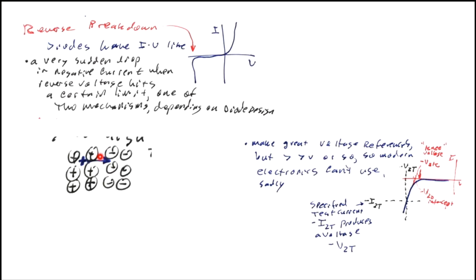And as that hole is accelerated across, it can get a lot of energy. Acceleration: the longer you keep accelerating it, the higher its energy becomes, right? It'll go faster and faster, and it'll get more and more energy. And so if you've got a large voltage across here, you've got a large field, and that can accelerate it a lot. It's not just the depletion built-in voltage that's going to do it. A large part of it is due to a large negative voltage.